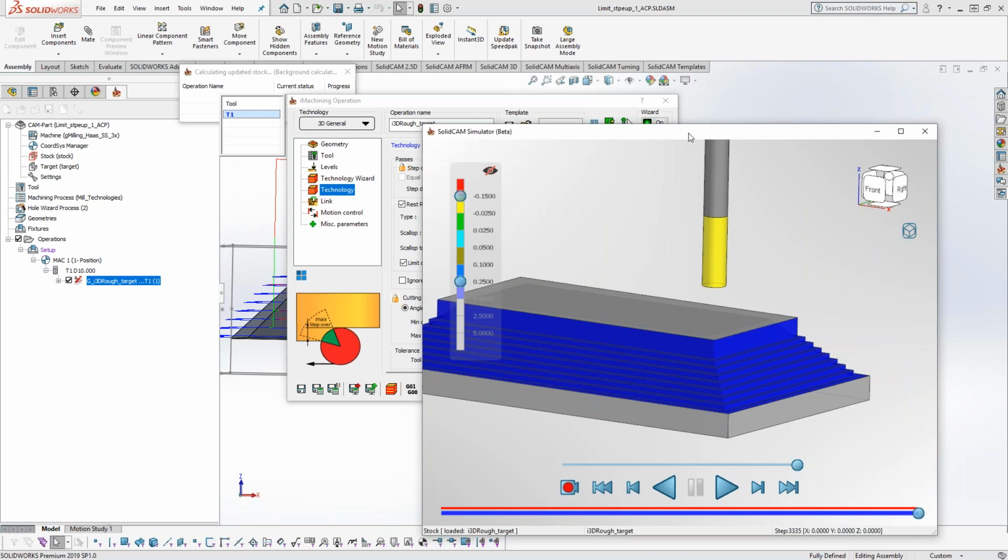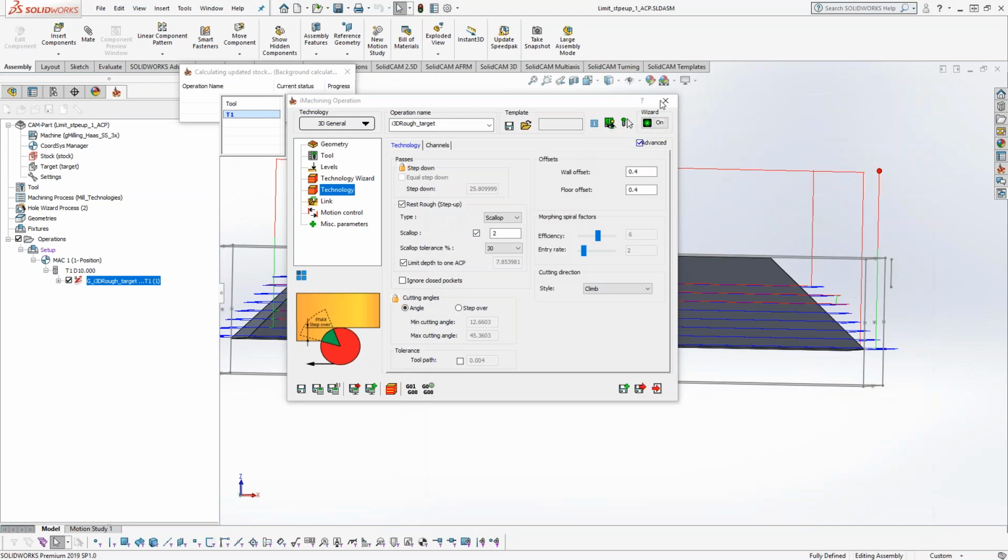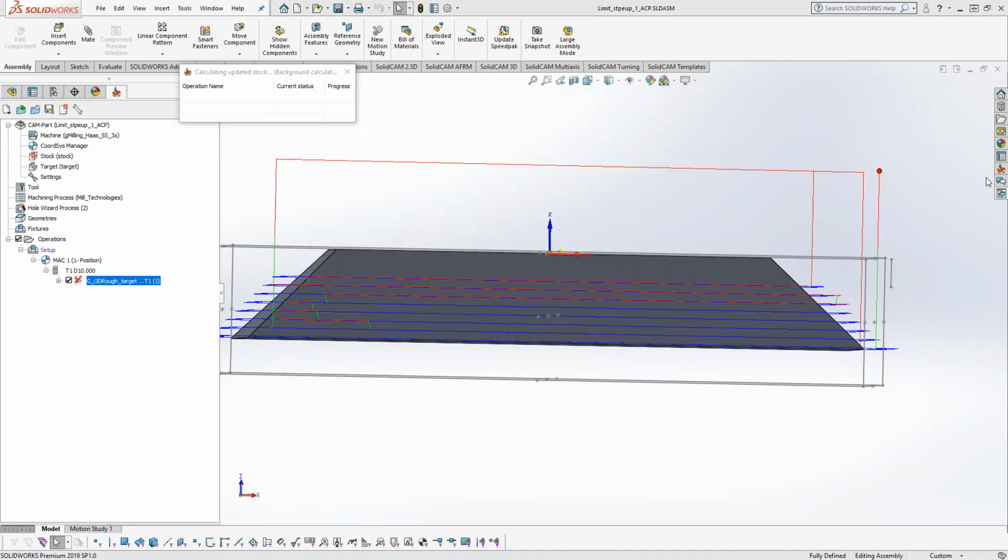Maybe you want to rough the part with your good quality end mill, and then come back with the same size tool that's maybe a little bit more general purpose, because there are different end mills. There are end mills that are good for iMachining style cutting, and then there are end mills that are a little bit more generic, that can take a little bit more abuse, but don't cut as well. So you could use an end mill like that to try and remove that rest material.